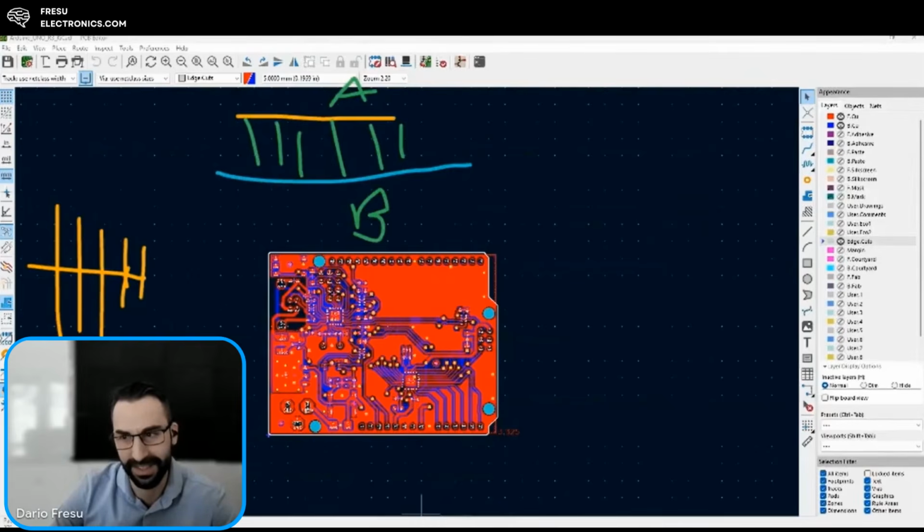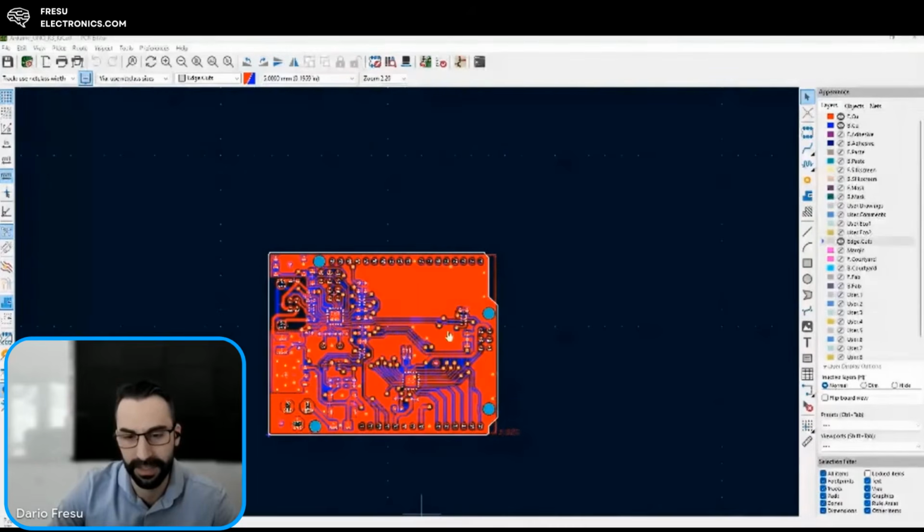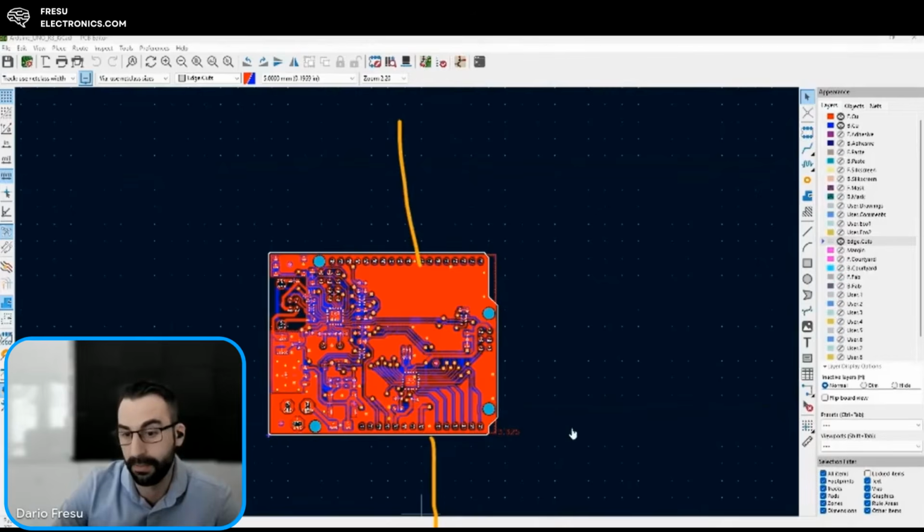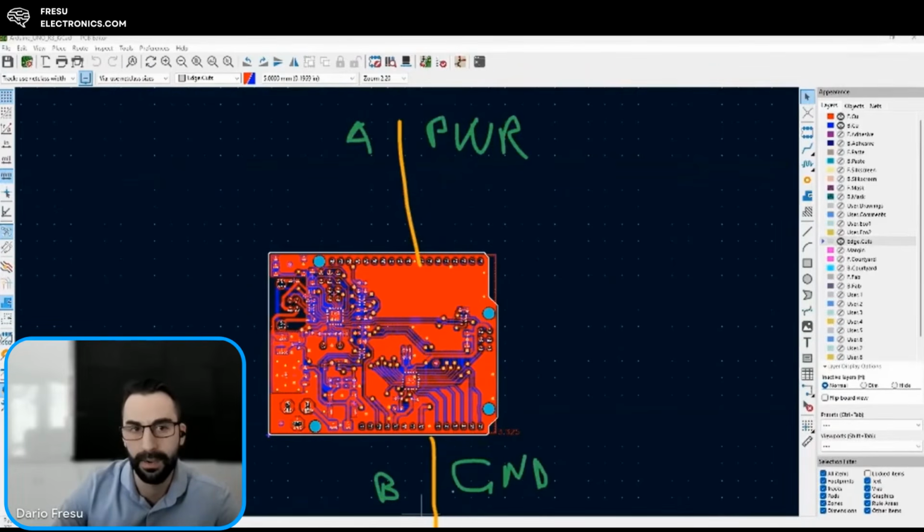Once we understand this, then look, it's going to become super simple also to understand how I'm going to place the cables. If this is the strategy that I need to use, this is the fundamental strategy that I can use to design printed circuit boards that pass electromagnetic compatibility straight away. So if I have the cables placed in this way, and I know that the fields are in between the cables, so if this is conductor A, this is conductor B, let's suppose this is power and this is the GND, how are the fields going to be established between these two conductors?